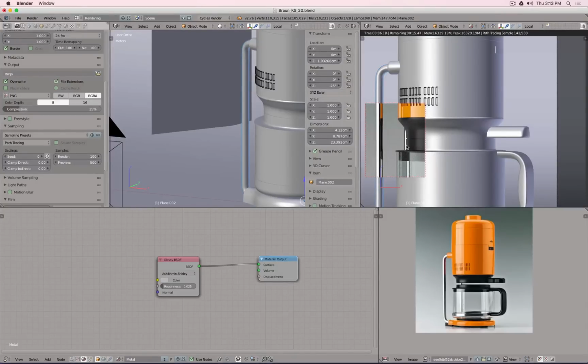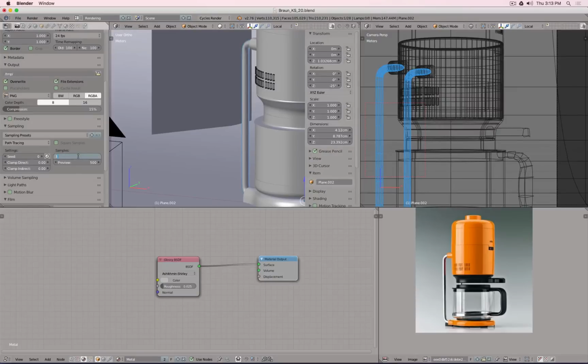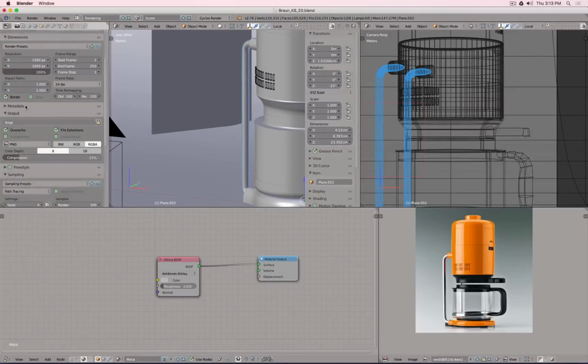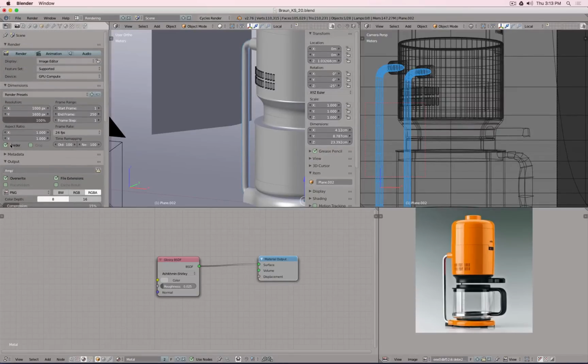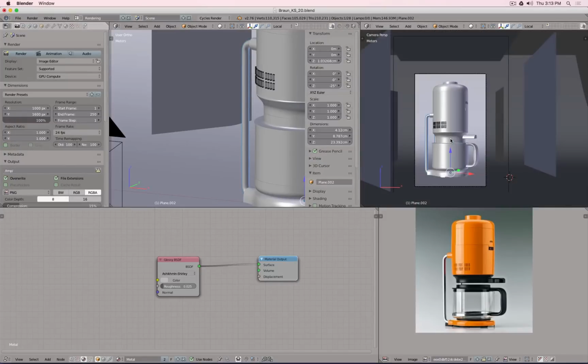Yeah, a similar area. Also keep in mind, a little bit of noise doesn't actually look bad. Feels a little bit like actual historic film. And also when you print, that noise you might not see. So also here 300. So 300 samples for rendering. I do not want to render the border, so I deactivate it. Let's save everything, and then let's hit render.